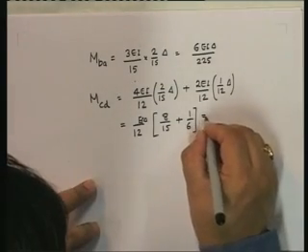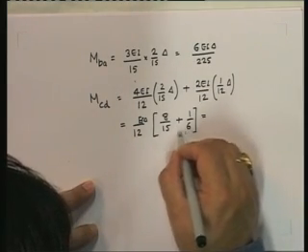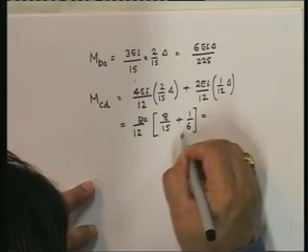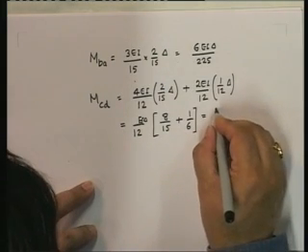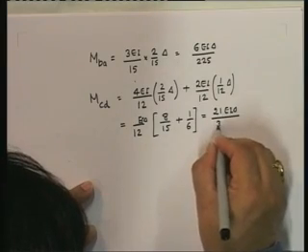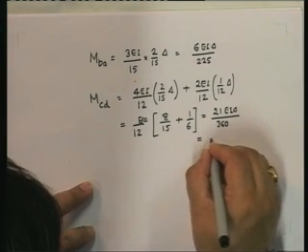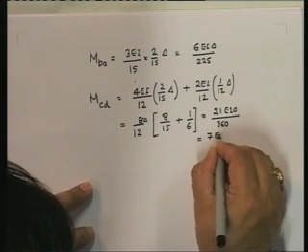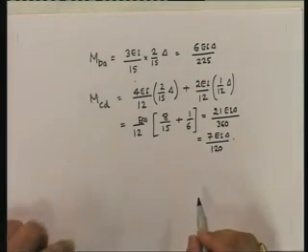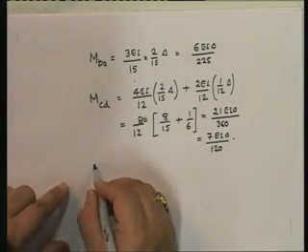So this is going to be equal to, 30 is the nearest. So 30 would make it 16, and this would make it 5. So 21 upon 30. So this would become 21 EI delta upon 360. Okay, which if you look at it becomes equal to 7 EI delta upon 120. Okay. So that is MCD and